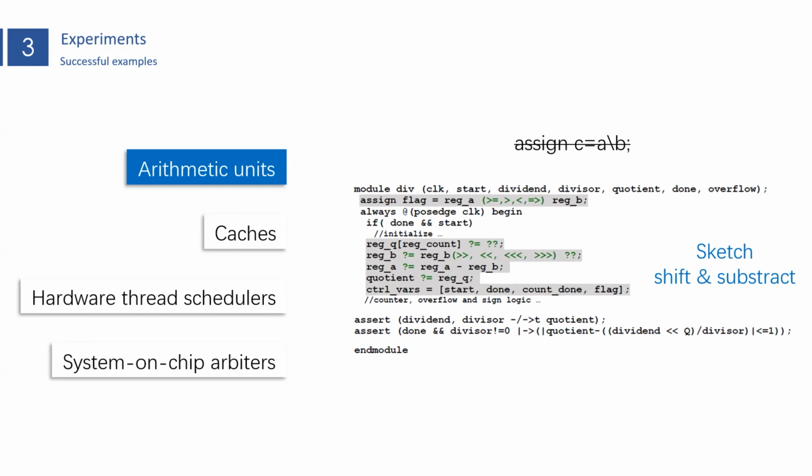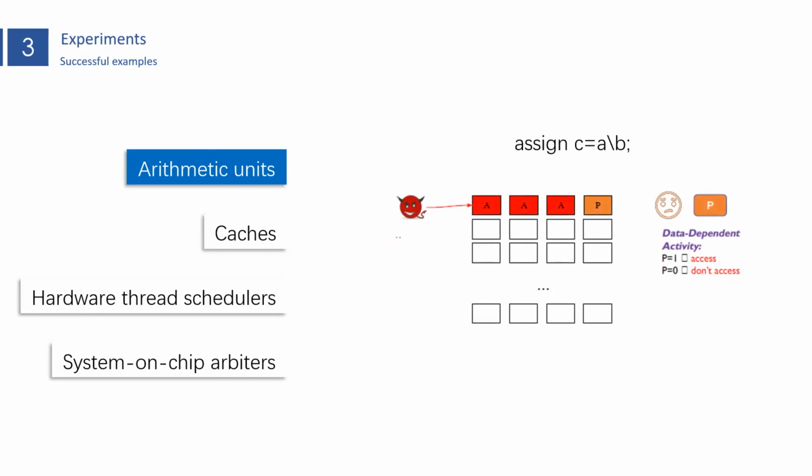But designing directly in this RTL will always lead to security problems. I'll just demonstrate it to you. Let me borrow this figure from the Professor's PPT. These arithmetic units run in multiple cycles, so they could have early termination based on the operand values. Let's say this is A divided by B. With different values of A and B, they can take different times to compute the value of C.